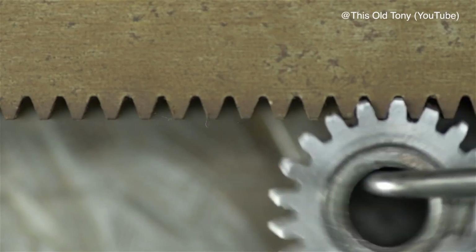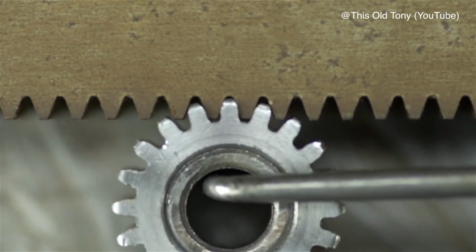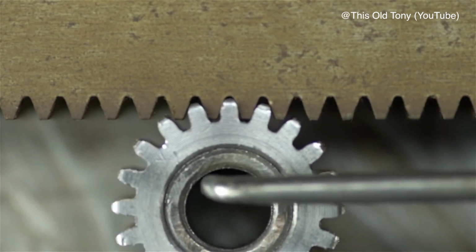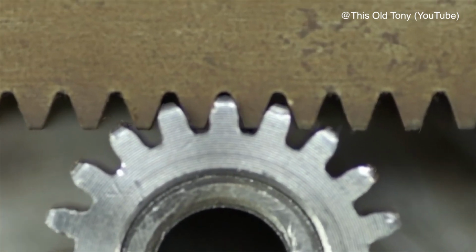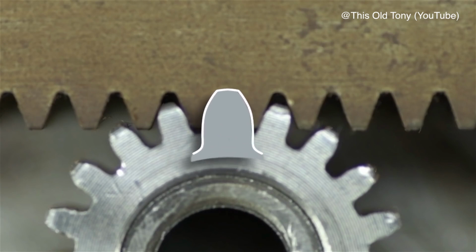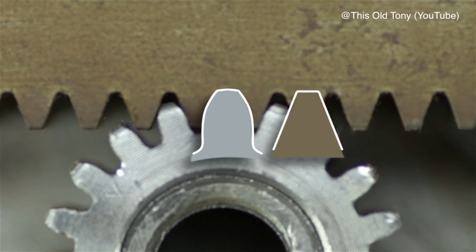To illustrate pitch, I have a couple of gears with an involute profile, a 12-tooth gear and a rack gear with infinite teeth. Think of a really big gear, then look at a close-up section. Note on the small pinion gear the curved involute profile of the tooth, and on the rack the straight profile of the tooth. These represent the extrema of gear profile, however, both have the same pitch.